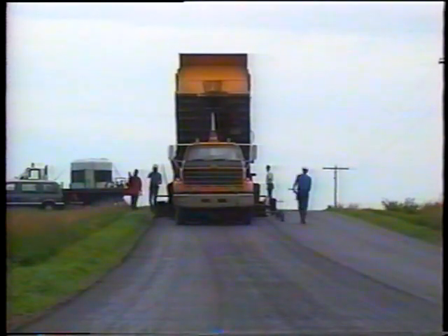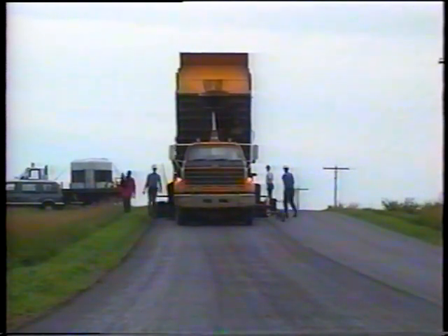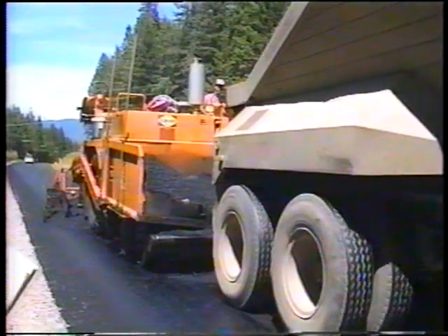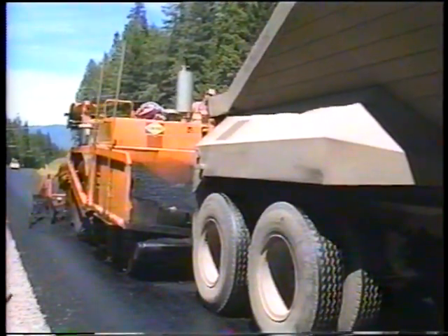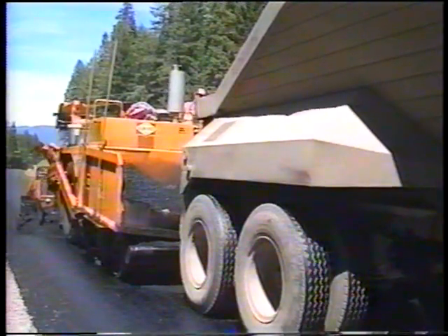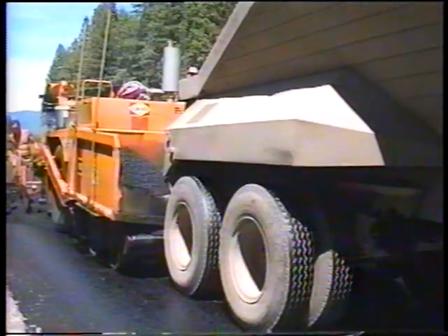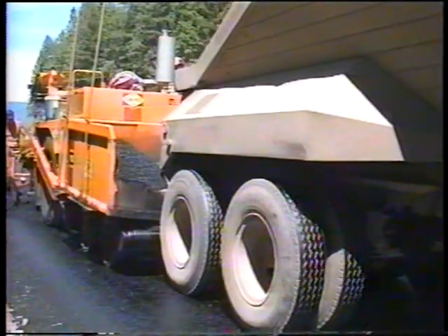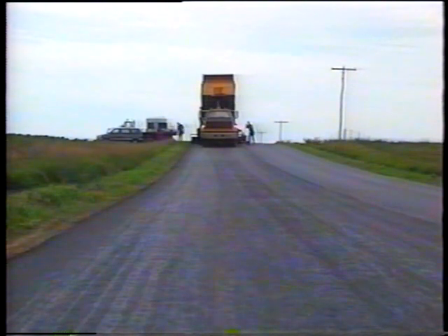Something that might take a little more skill for the truck driver is working on hills. Remember, in most cases, the truck backs up to within a meter or so of the paver and stops. The paver moves ahead and pushes the truck while the truck loads the hopper. That's simple enough on flat ground. But when going down a hill, the truck driver needs to apply the brakes, or the truck will pull ahead of the paver and spill the mix.